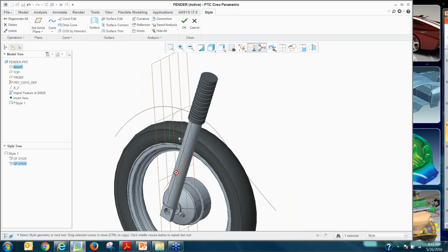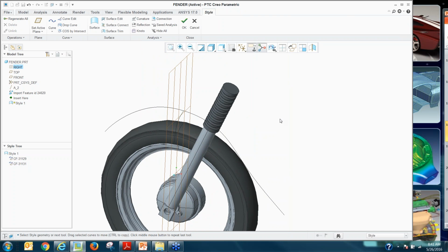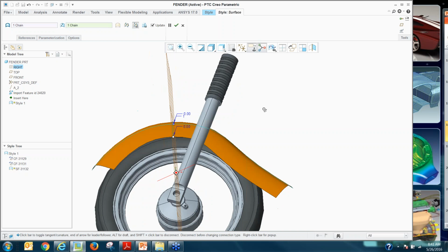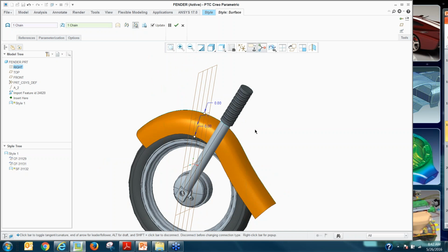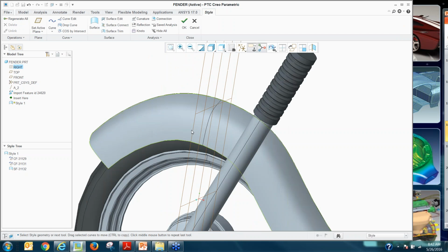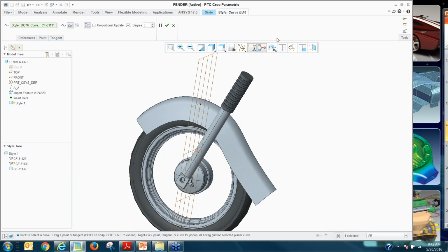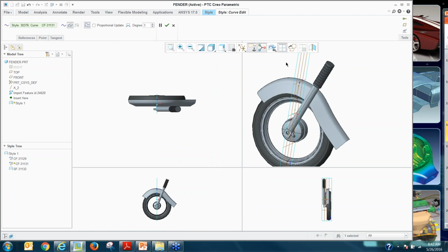So what I did really quickly is I created a couple of curves there, and now all I'm going to do is do a surface, right? So let's say I want that to add as a cross collector right there, right? So I've added that surface. Now, having done this, I can always go and manipulate that curve. Maybe I want to add a few more points, or I can modify that, and I can use a 4-view layout to do all that.